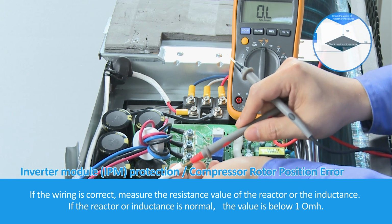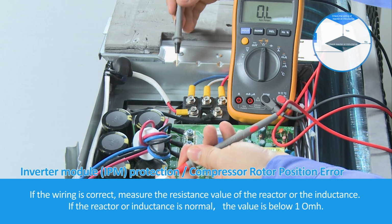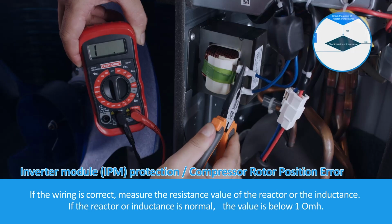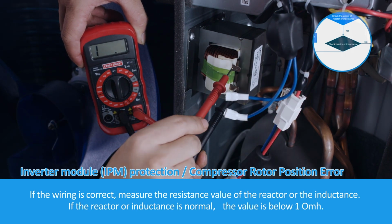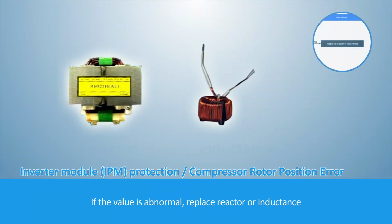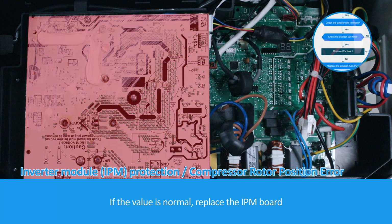If the reactor or inductance is normal, the value is below 1 ohm. If the value is abnormal, replace the reactor or inductance. If the value is normal, replace the IPM board.